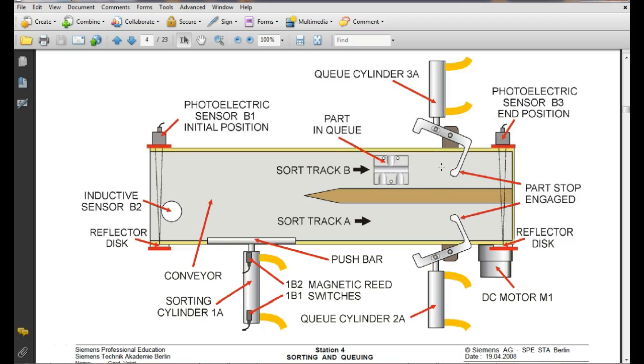Yeah, but you've got to understand, 95% of the time the timer works. I mean, probably even higher than that. So what's the advantage of using open loop over closed loop? Yeah, it's cheaper. So this is what you've got to learn right off the bat. Sensors are great, but if they can get by without a sensor, if they can get by open loop, they're going to do it open loop, right? Y'all understand that? Because why? Yeah, it's a lot of money.